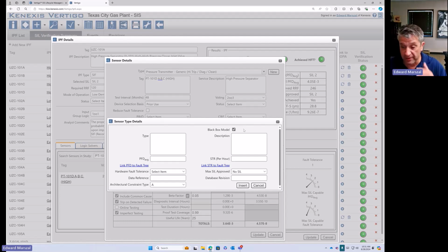probability of failure and the spurious trip rate of their system, because their systems are very complex, and no canned software, for instance, will model a Triconex correctly. Ask them yourself if you don't believe me. They have their own proprietary Markov models that the other software vendors don't have access to. So instead, they want you to go to them, and they will calculate the PFD and the spurious trip rate of the system